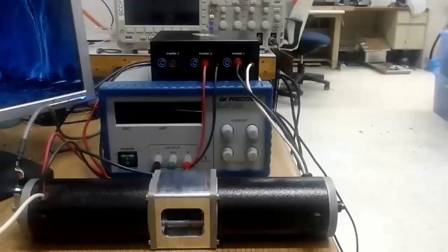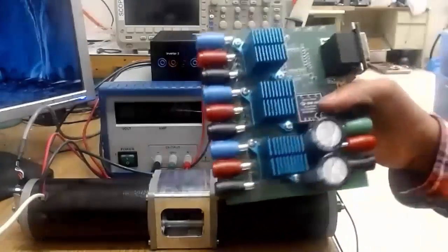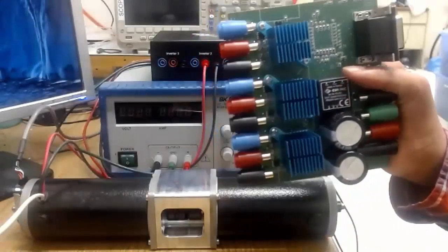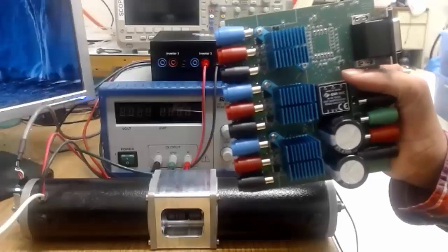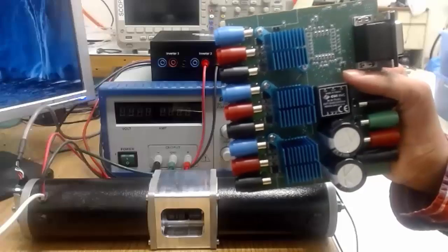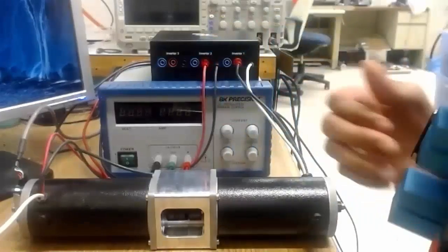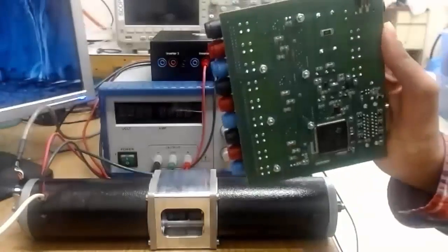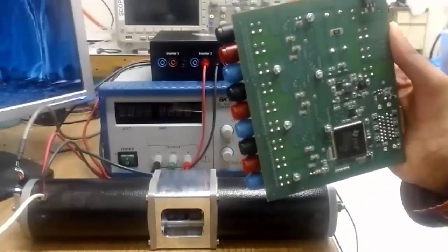The speed of this coupled motor generator set is measured using a 2048 line A quad B encoder, and the data is fed back into the controller on board the inverter on the top here. The inverter is rated for 50 volts, 10 ampere operation. Here is what's inside the inverter module. It consists of 3 3-phase inverters that enables us to run a doubly fed induction generator under vector control, in addition allowing us to control a coupled motor as well to emulate a load. This inverter also has a controller on board that allows us to implement all of the control algorithms digitally.